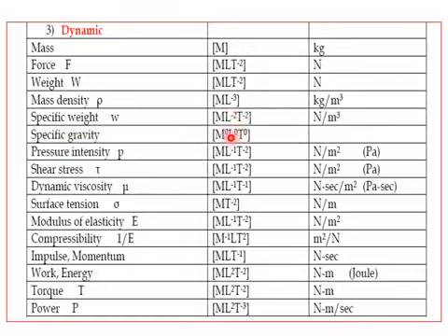Specific gravity has no dimensions, so it is M to the power of 0, L to the power of 0, T to the power of 0. Pressure intensity is force by area, so if you take force and divide by area, you will get ML^-1 T^-2. Similarly, shear stress, you know that it is again force by area, so same units. So dynamic viscosity mu is Newton second per meter square, so you can get the units. That is ML^-1 T^-1.